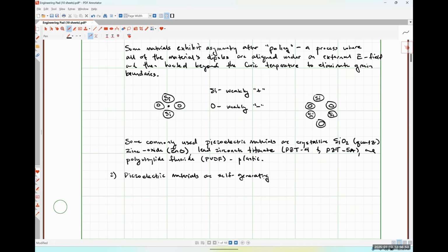So generally speaking, the output of a piezoelectric sensor is going to be fed into some sort of buffer amplifier, so that it can draw current from external power supplies to be used to do things. So if we need anything other than just a strict voltage, we need something else to help us out on the current front, okay?